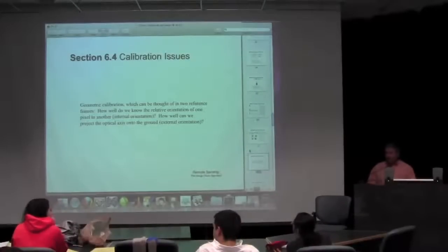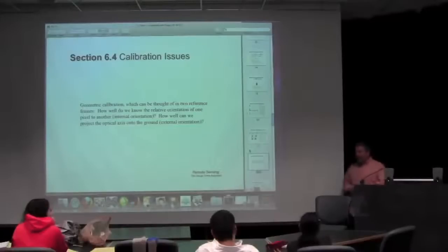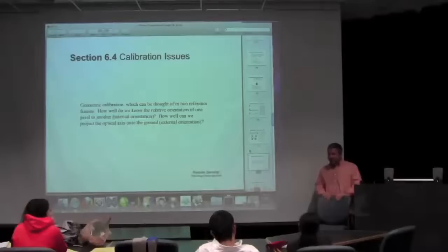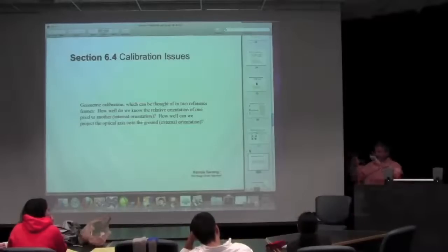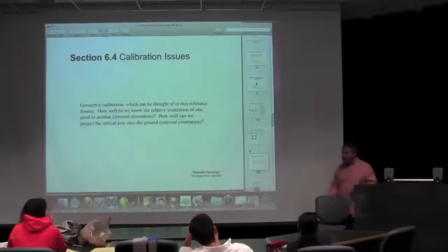So there's onboard characterization of the smile? I haven't seen anybody do an onboard spectral characterization. That would imply having a monochromator and a calibrated light source and everything on board. Yeah, it's just more elements. For everything, the more elements you add to it, the more space. Oh, absolutely, and sheer size. Because we'll talk about calibration here in a second, but entrance apertures to these devices are usually pretty big. And that means you have to have integrating spheres that have openings that big, which means they're about that big. So that's when you're having problems.